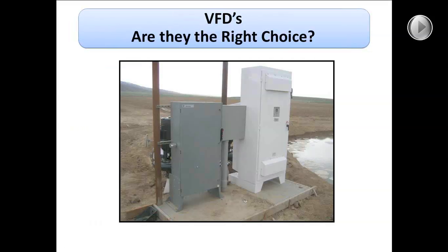I'd like to talk about VFDs for a minute. VFDs, at least in eastern Idaho, have been really popular lately. And they sure do make managing an irrigation system and operating it, they sure are nice for that. Like I said before, the most typical application is you set a pump pressure, and it just constantly maintains that pressure.